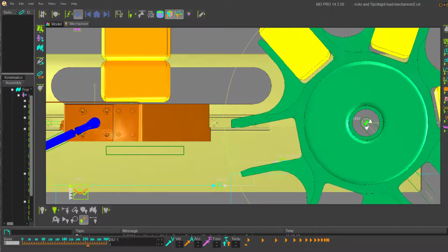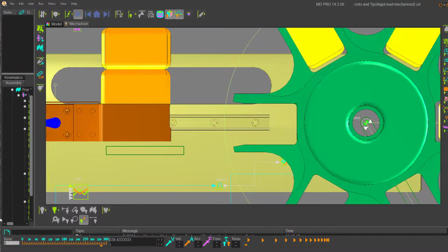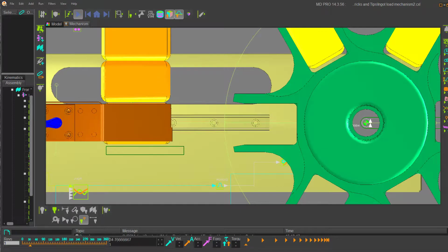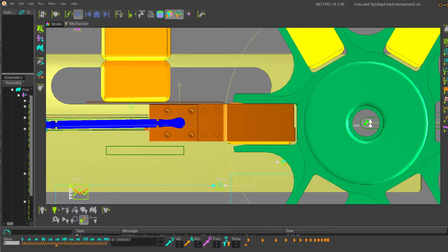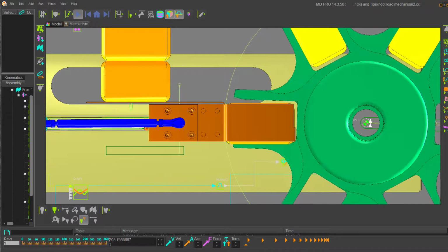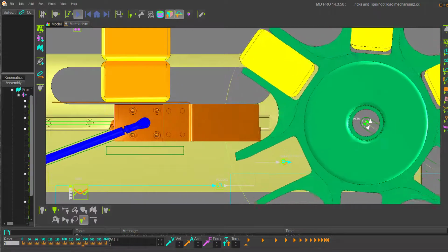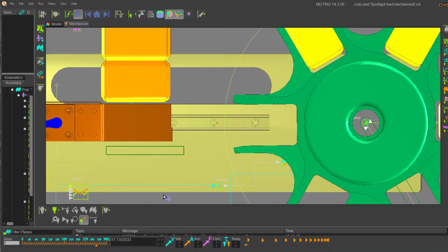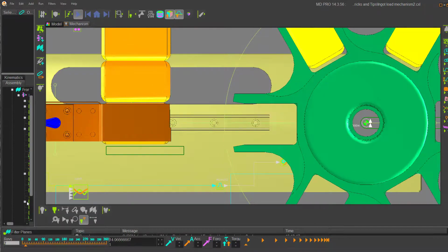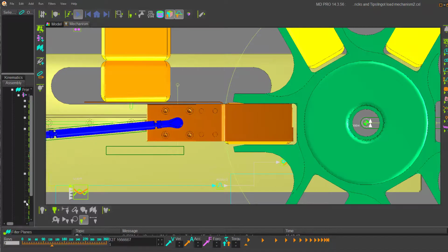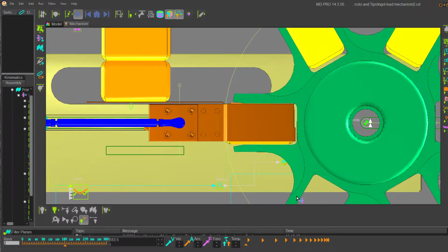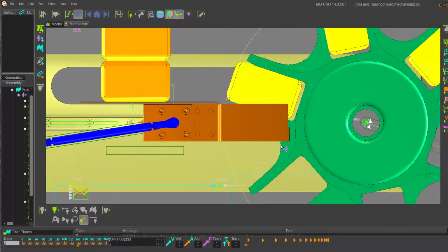Oh, its retraction is still catching a little bit on the return. So in it goes. Okay, so I think there's still time. We can perhaps advance the indexing turret even further, but it is just fouling on the end here. Just if you watch this, insertion, turret indexes, and then it just catches the pocket. The pusher just catches the pocket here.